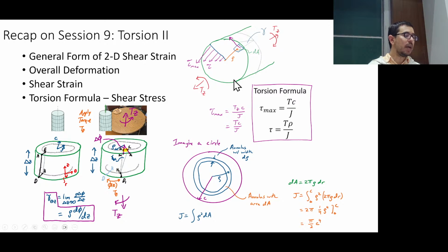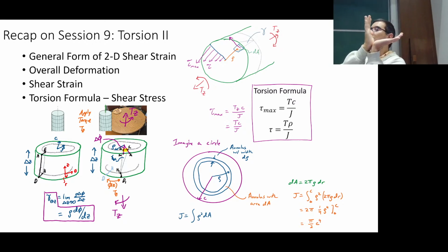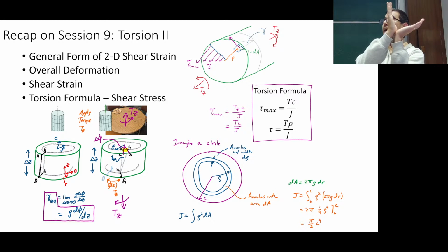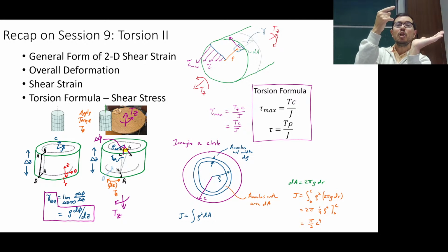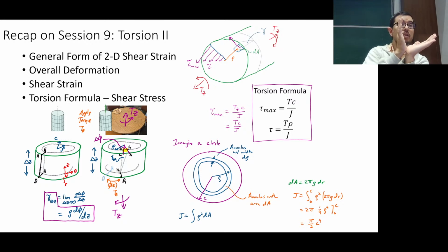Okay. Which directions are we looking? So if it was in the Z face in the Z direction, that would be a normal stress, right? Yeah, exactly. So we're thinking X or Y. All right, and this is where it gets a little bit tricky, okay? Because X or Y, I've got this face and I've got my X and my Y, and my shoulders are bad, but I'll use my hands. So I got this face coming out, I've got X or Y. My max stress is going to be when my stress that I'm calculating is in the same direction as one of the coordinate systems, either the X direction or the Y direction.